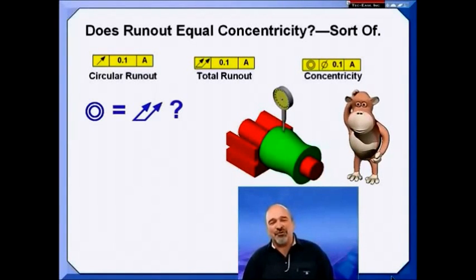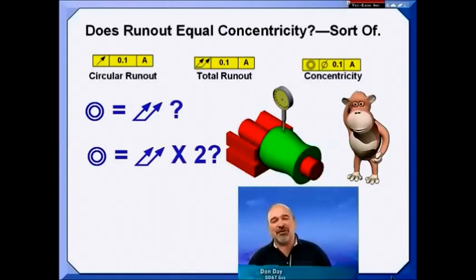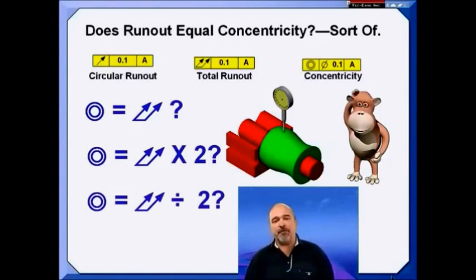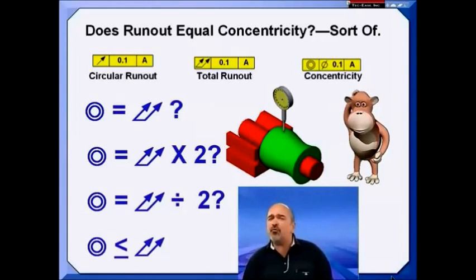Years ago, there was no difference between concentricity and runout. They had the same definition. Over the years, this has changed. However, you can still use runout measurement to verify concentricity.